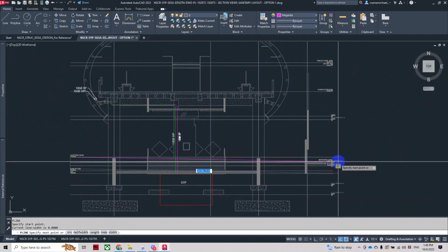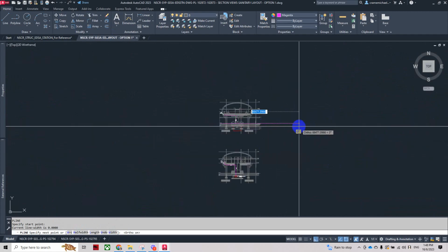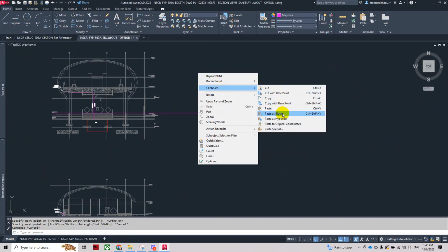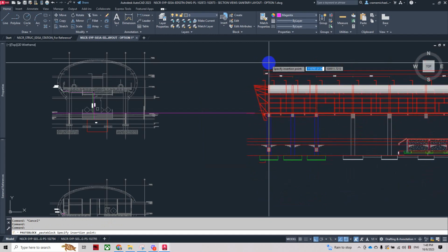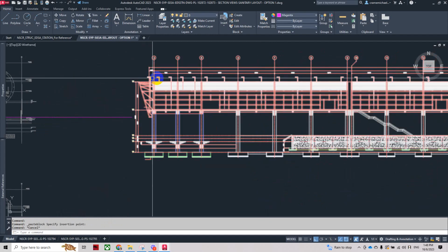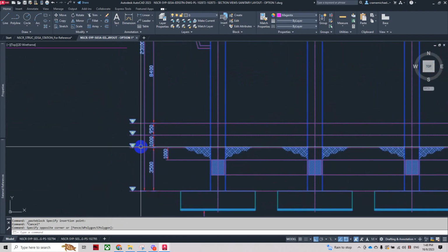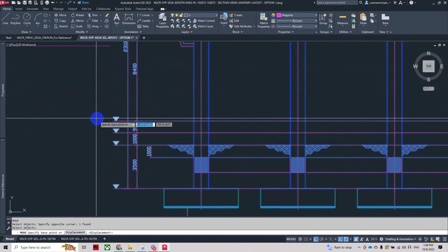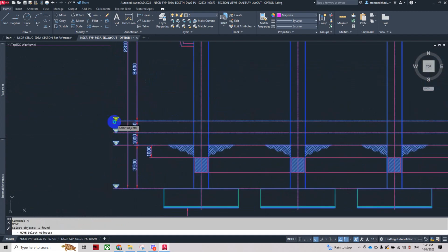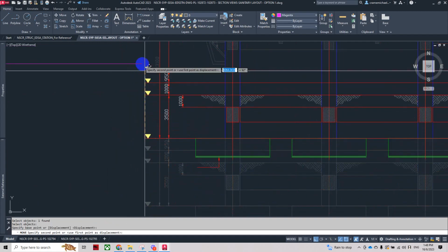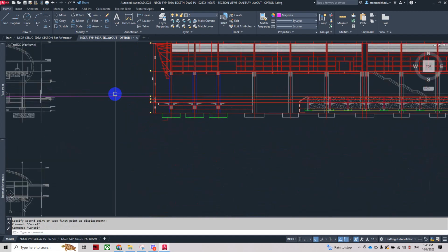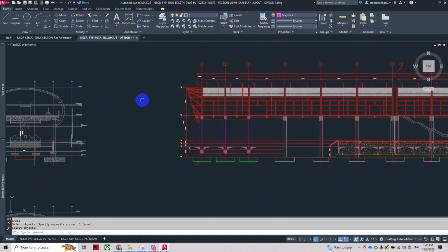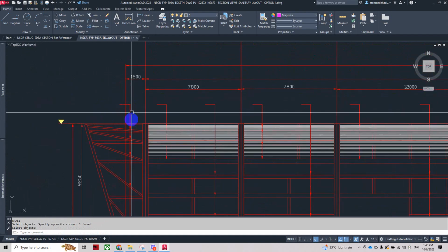So we just only copy the structural framing. So here we're going to create a line for reference of the platform level. Here we're going to paste our structural frame or structural sections. So currently, as you can see, I paste it as a black, and all the colors are still in different colors based on the previous or original drawing file. So pasting it as a group is much easier, so we don't have to explode each element, and we can go in and change the properties later.